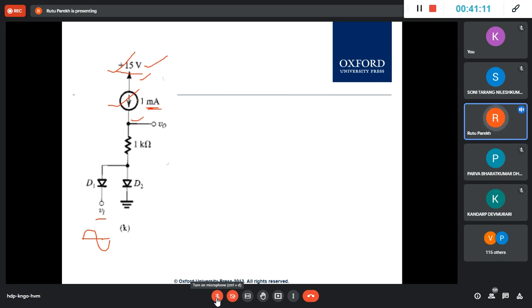Remember one thing, you cannot buy a current source the way we do. We have to make a current source using transistors like BJT, let's say, or now in circuits MOSFET, and a voltage source. When you make this, there is a circuit equivalent to this. There are a few transistors connected through a voltage source, and the current that will pass is 1 milli.